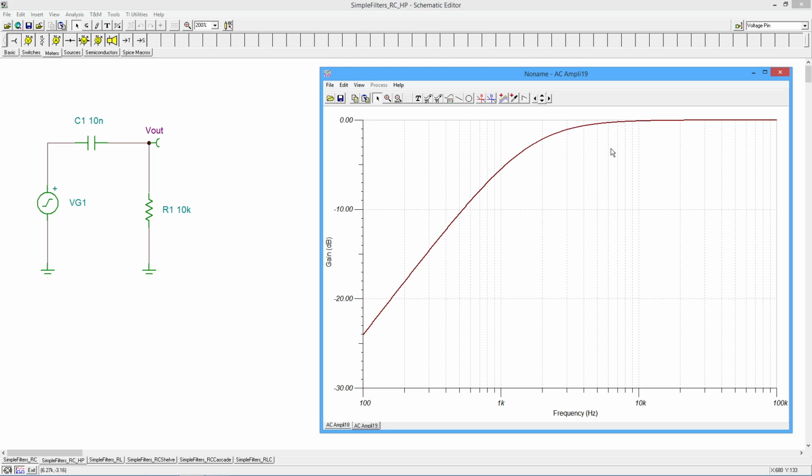And there we go. All right, so our low frequencies are limited. And once again, same values, we'll get the same critical frequency. So I'll just, again, throw this out here and try to find our -3 point right around there. So again, 1.59 roughly. I'm just estimating these. Okay, so I'll do a quick compare.